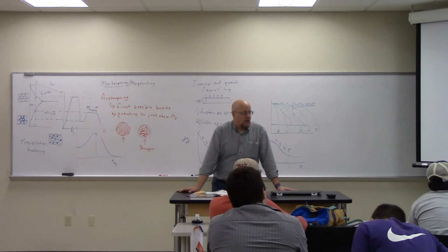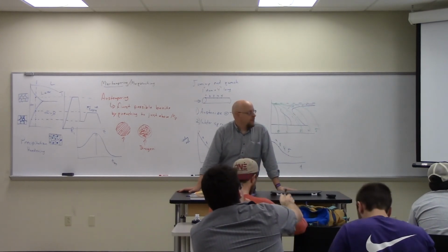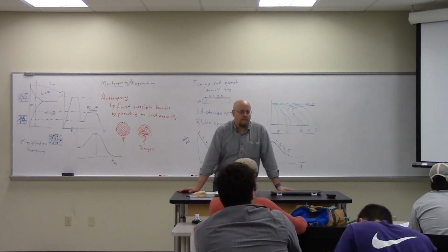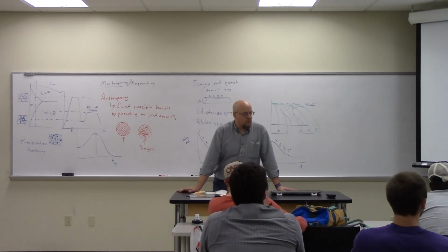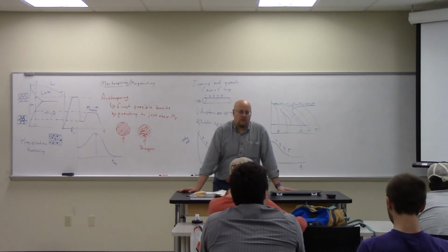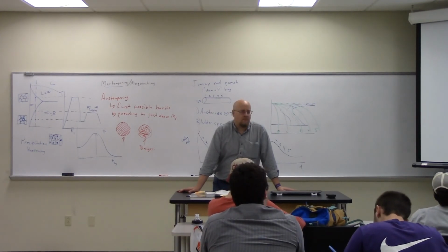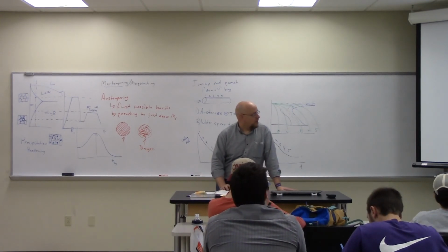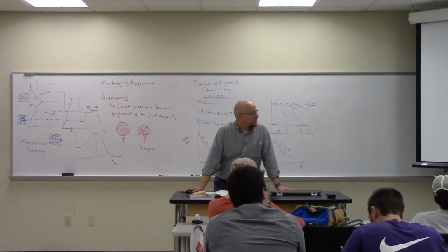So what do you think that's going to look like? Just a line from the left edge at 727 all the way down to the 1 day mark on the right edge. Straight line, if it's a constant cooling rate? No, it's a curve because it's on a log scale. So I've taken the liberty of showing such a curve. There it goes. So that's what it does.